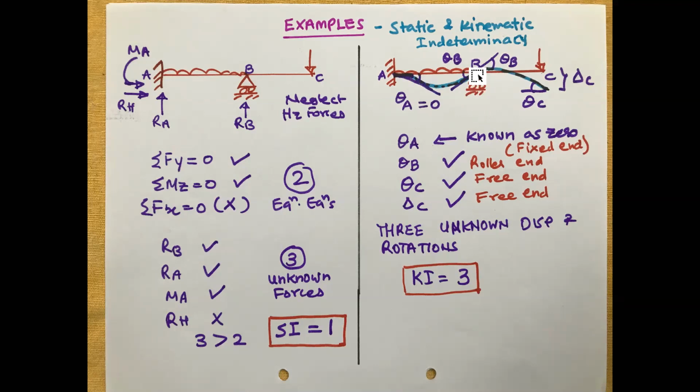Second, you can come here, second joint at support B, roller support. Now you know there is a vertical reaction here. You can't actually calculate deflection. Vertical deflection is known to us because I know a roller support cannot translate vertically. Vertical deflection will be 0. So delta B will be 0. But there is a rotation because it is a roller support. So this rotation theta B at the roller support will cause the left span and the right span to rotate.